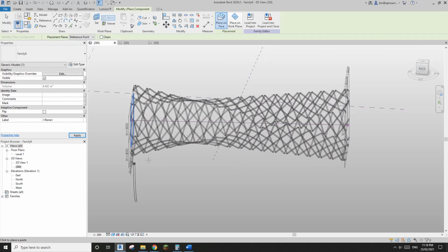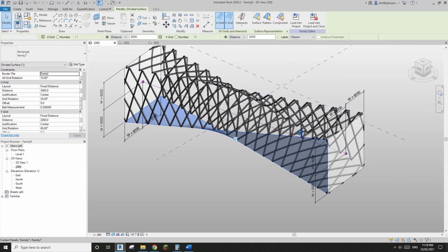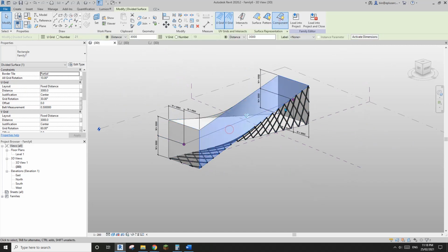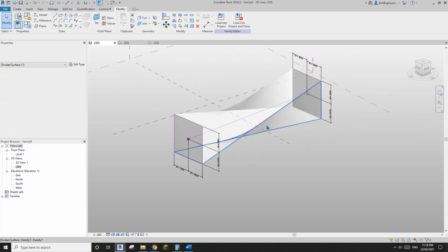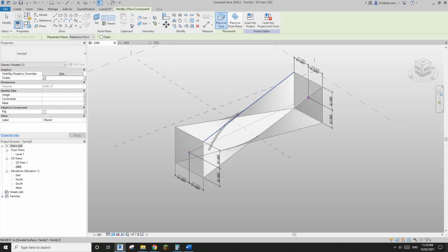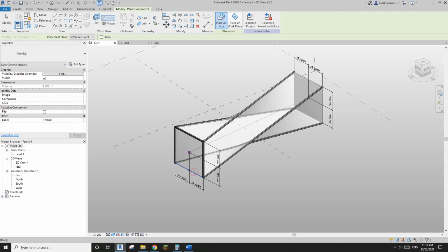And now we can manually place them. So before I place, I'll just turn off these smaller beams. Okay, so it's easier for me to pick. Now create component. I'll use SE, pick the end point, and then SM, pick the middle point, then SE, tab, pick again. So SE, SM, SE, tab, and I repeat this sequence for each of the remaining beams.